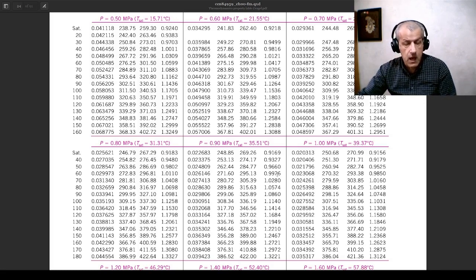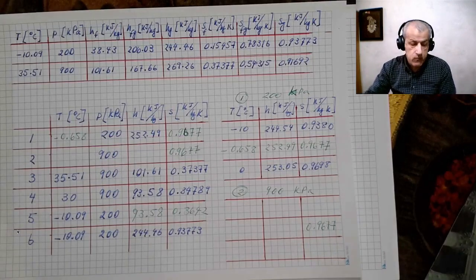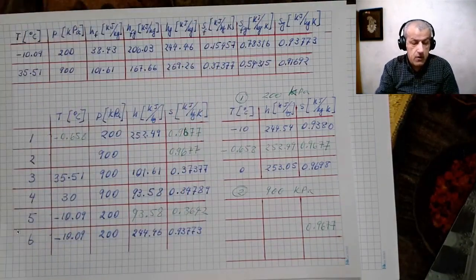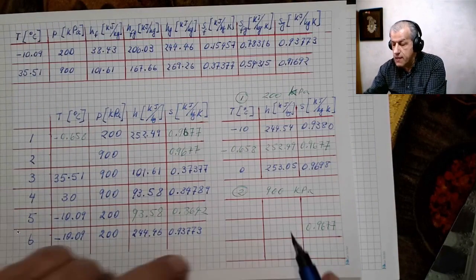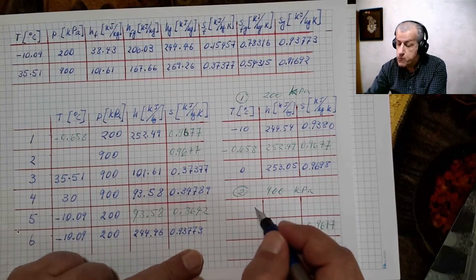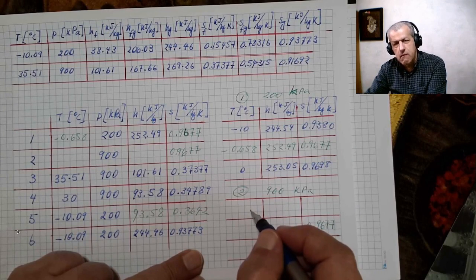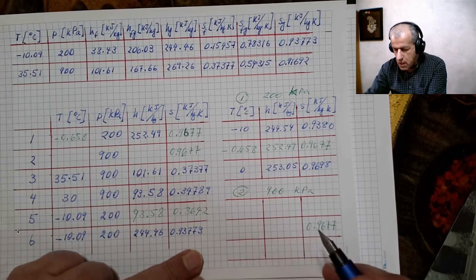But what I would do is write down the values above and below, the values for 50 and 60 degrees C in a table, and interpolate just to make sure that we are doing the right thing. But please note that for all intents and purposes, we wouldn't gain any accuracy from losing about half a degree.